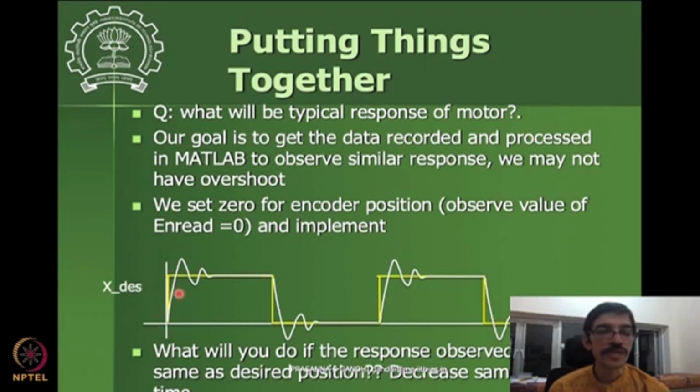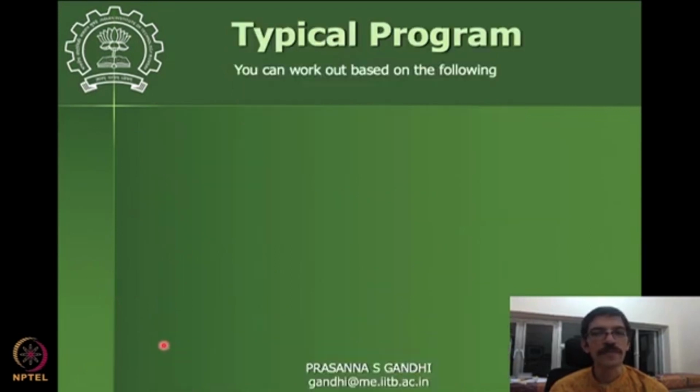But if your inertia is too low, then the sampling time that you have chosen might be too large for capturing the initial transient typical of a first order response. So you may find that the waveform for the speed is now coming as a straight line. Then you need to decrease the sampling time to make sure that you are able to observe that transient. These are small tricks that you'll need to learn as you build your practical understanding of the system.